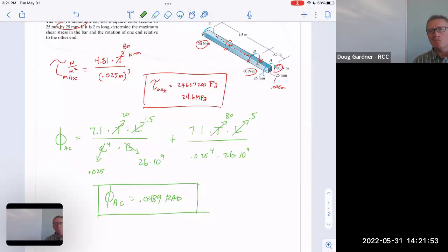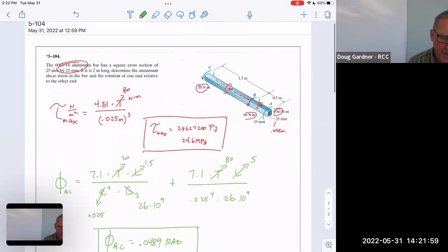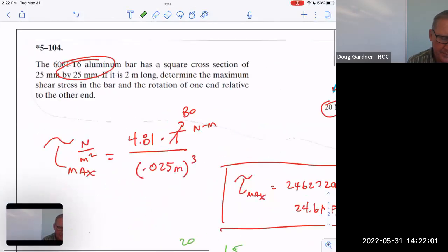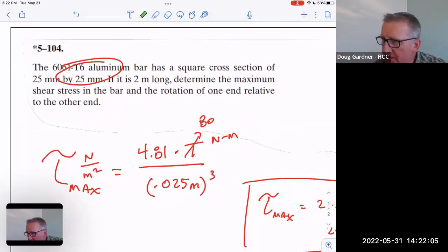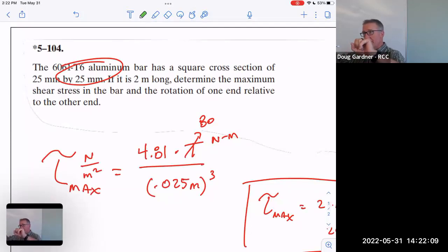Like we have our sigma, if we go past a certain stress, then the whole thing is not going to return. So if this twist is too much, it's not going to twist back. And that's where these limitations would come from, because usually you'd say, I want this material to stay in the elastic region, which basically means when I let go, it goes back to normal. If you get beyond that, then it doesn't go all the way back to normal.